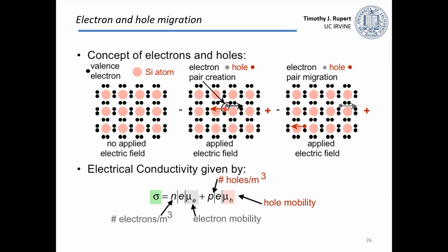So in this case, where there used to be an electron right here, it's jumped out and starting to move to the right. And when it does that, it creates a hole at the site where it used to be. Now, as we go forward in time, that electron keeps migrating to the right, that hole keeps migrating to the left, and eventually we're carrying charge through the sample. So this electrical conductivity in a semiconductor is really from a combination of effects.